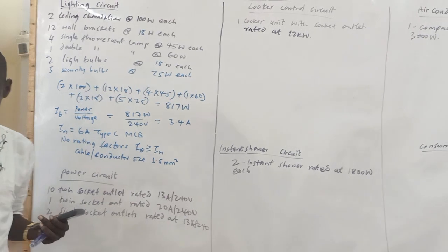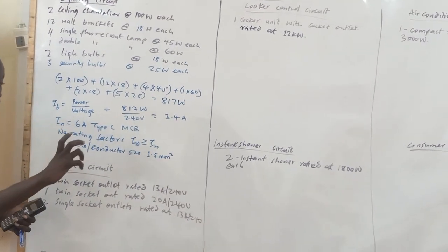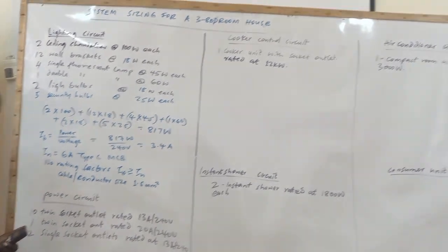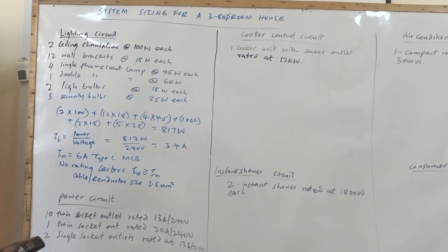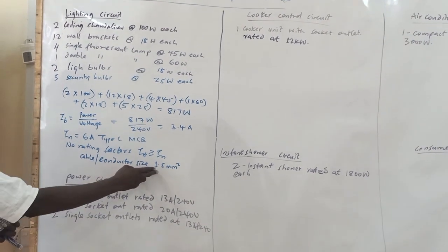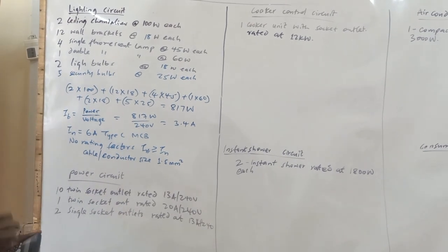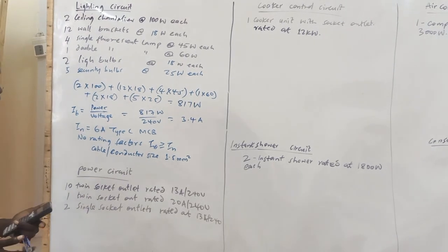In the previous video on sizing, I was able to give you a table and even show how to trace the figures. So that's how we do it. With this, you can now go ahead and calculate the voltage drop. But since this is a small cable, the voltage drop gives an allowance of even more than 100 meters run for the conduit. So that will not be a problem.